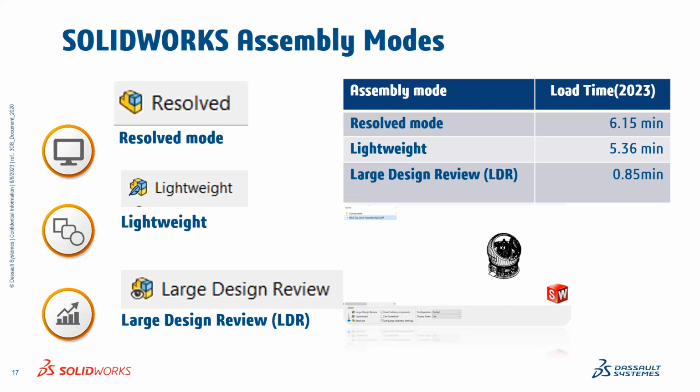In the resolved mode, I will just give you a brief. Once you open the assembly in resolved mode, it takes all the information: all the model data, model features, and model information as well. In lightweight, there are many options available, but you will not get complete data information.